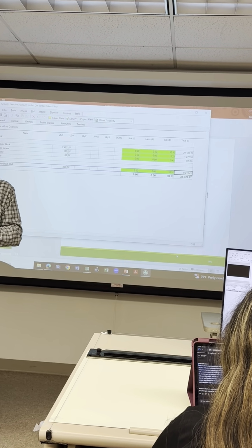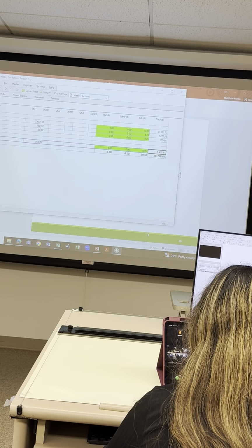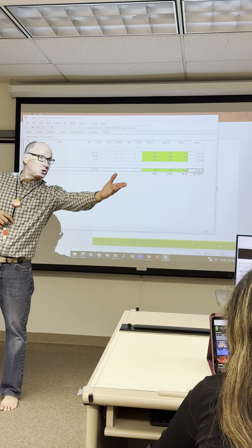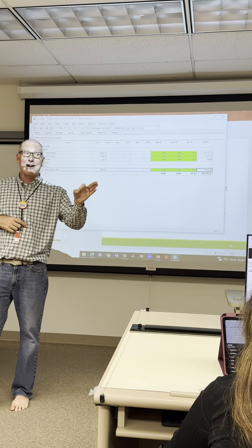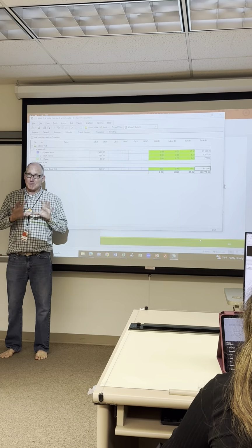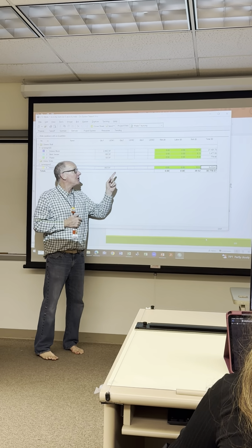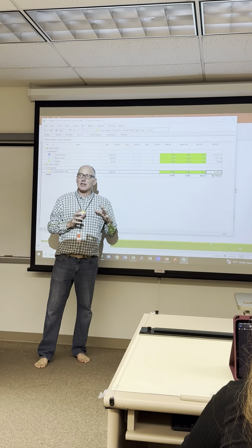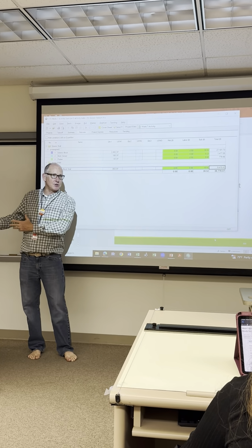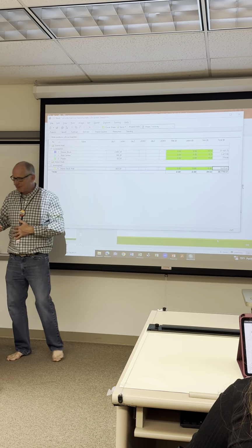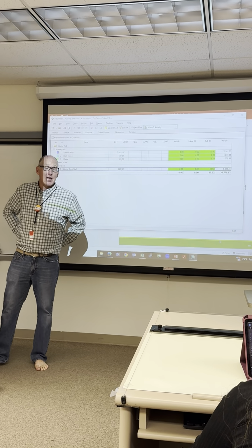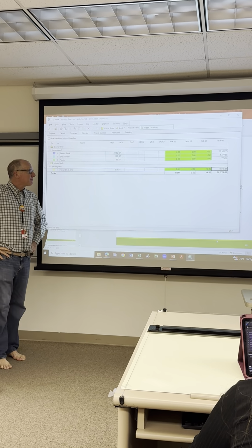That structural steel, if you want, insert that structural steel, and you could do a linear quantity. You could do quantity takeoffs to achieve total length, if that's what you want to do. But you gotta be careful. You gotta do total length of the same steel designation. Gotta be a little tricky there. Now here, I'll share in the summary. The calculations are limited. So it'll give you total length, but you gotta migrate that over to a spreadsheet. It'd be an excellent QC/QA, say, did I do a proper takeoff? It's an excellent second estimate. Questions?